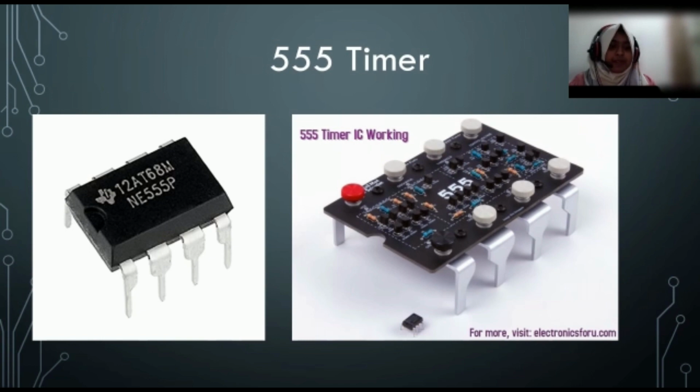The 555 timer IC is an integrated circuit used in a variety of timer, delay, pulse generator, and oscillation applications. The 555 timer IC is a very cheap, popular, and useful precision timer device which can act as either a simple timer to generate a single pulse or long time delays, or as a relaxation oscillator producing a string of waveforms of varying duty cycle from 50 to 100%.